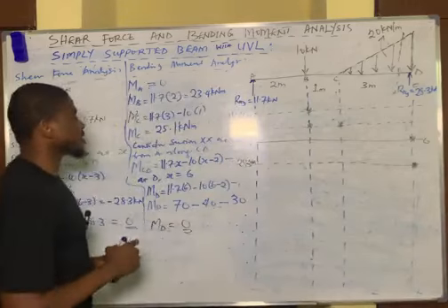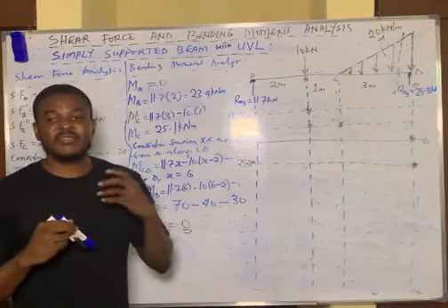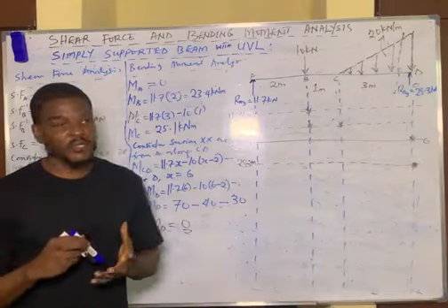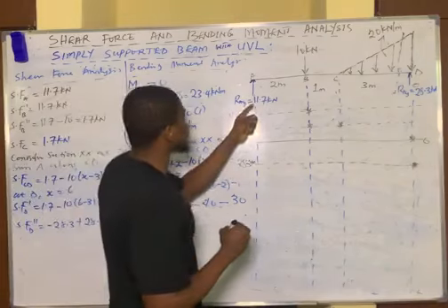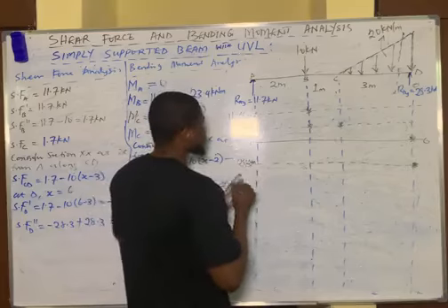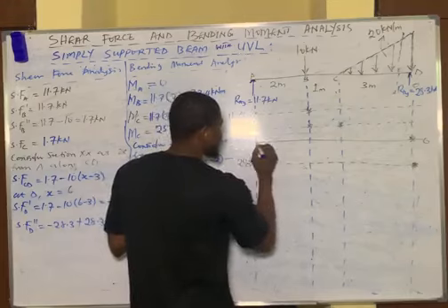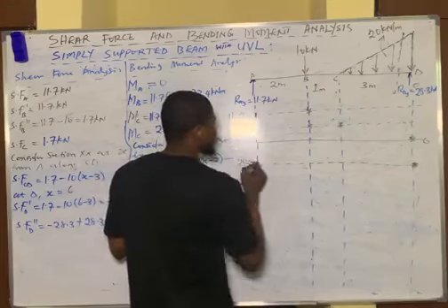So let's now connect the points. The shear force diagram for a point load is simply a straight line connecting each of the points. So I have a point load here, RAY. So from the origin, you draw a straight line to connect to this asterisk point. So a straight line to connect the points. You have this.